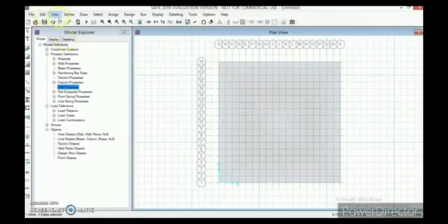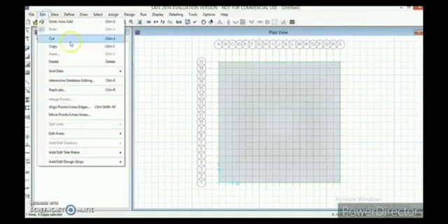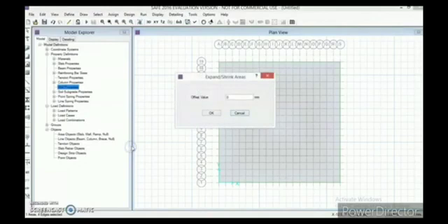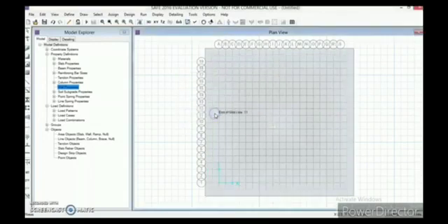And now I am editing it. Actually I need to enlarge this area to 22 meters. So I am editing it. So edit areas, expand or shrink areas. I need to extend it with about 2 meters, which is equal to 2000 mm. So click on OK. So now my extended plan view is displayed here.